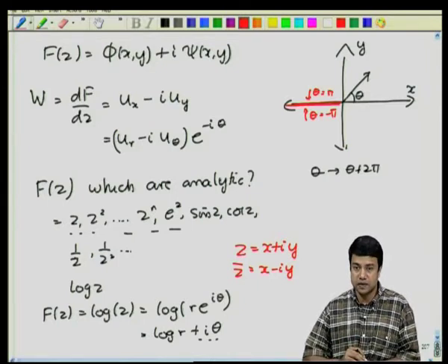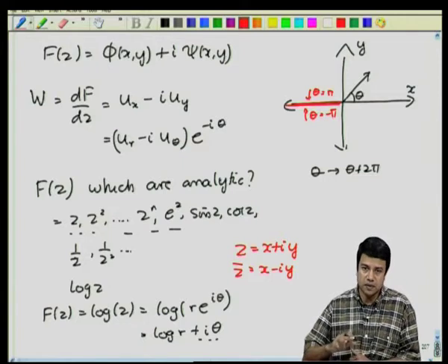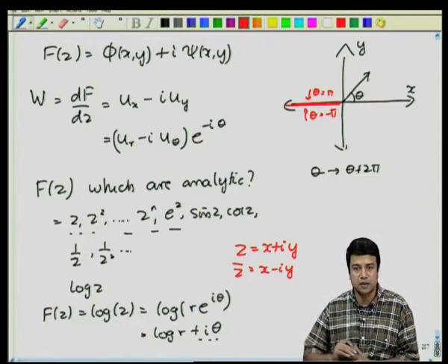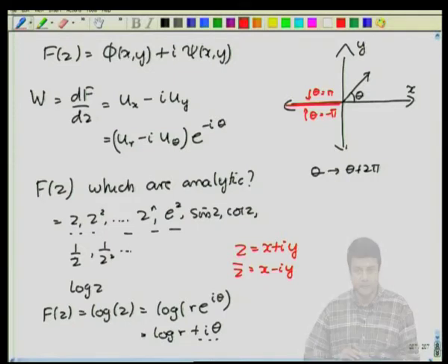So, we have this range of analytic functions, which represent potential flows, and we can ask for this particular form of the function, what kind of potential flow do I get. So, in the next lecture we will look at that question. I choose a particular form for the function, and I try to see what is the kind of potential flow that results for this particular form of the function. And by identifying boundaries on which the normal velocity is equal to 0, I can find out what kinds of flow result from specific values of these complex functions. So, that we will continue in the next lecture, what kind of potential flows result from specific forms of complex functions. We will look at potential flows in 2 dimensions using this complex plane.